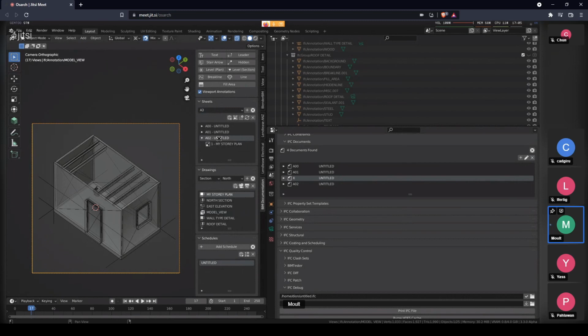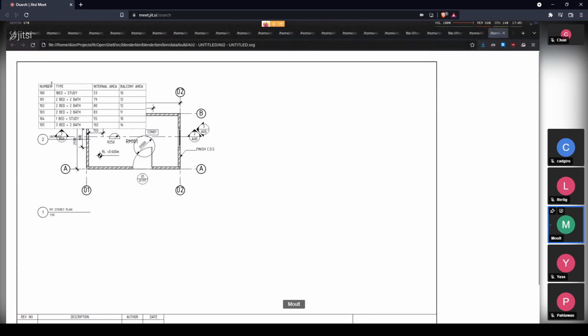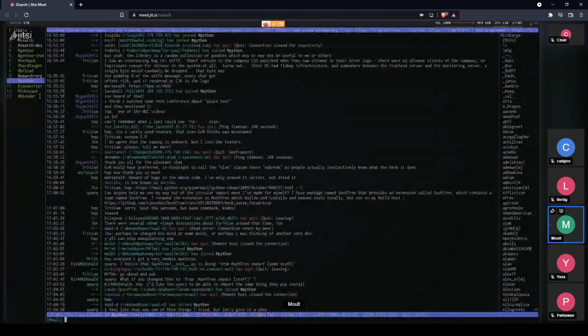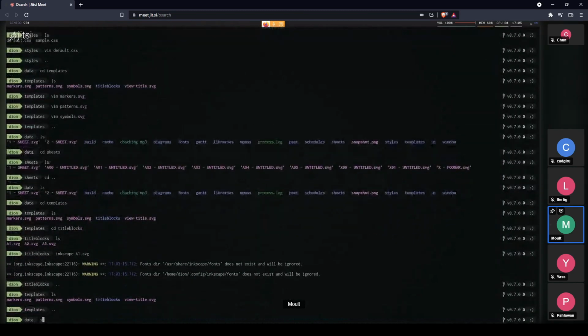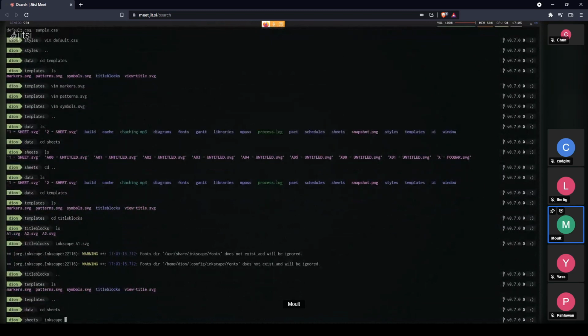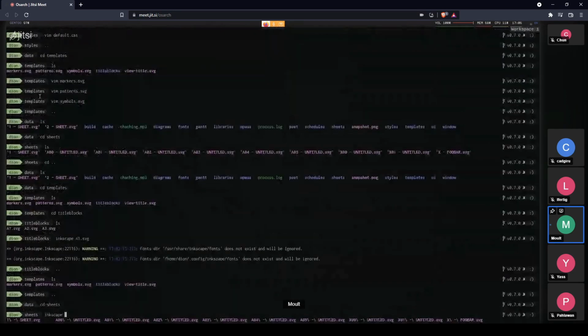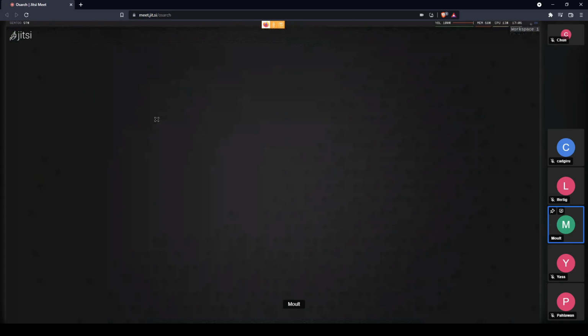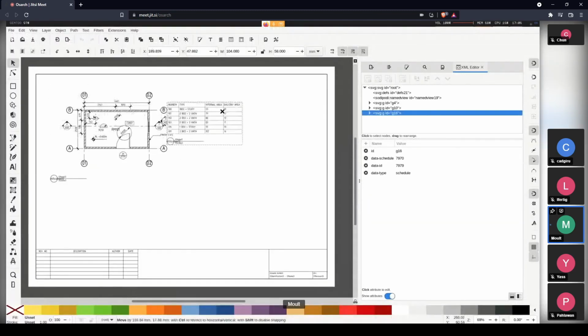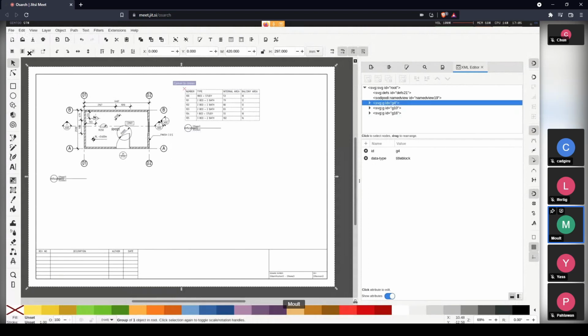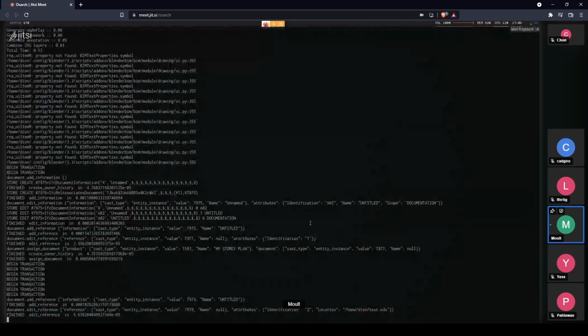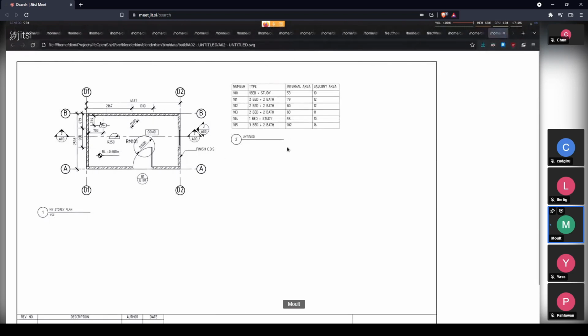If I select the spreadsheet, select this sheet, I can press this button to add a schedule to the sheet. Now I have it, and it overlaps right now. So I'll need to go in Inkscape and just shift that over. Everything it generates is in a folder called Sheets. So I can open, what's this sheet called? AO2 Untitled. Okay, AO2 Untitled, great. So in Inkscape, I can just take that and say, plonk it here and save. And now if I regenerate that, you can see it's moved.